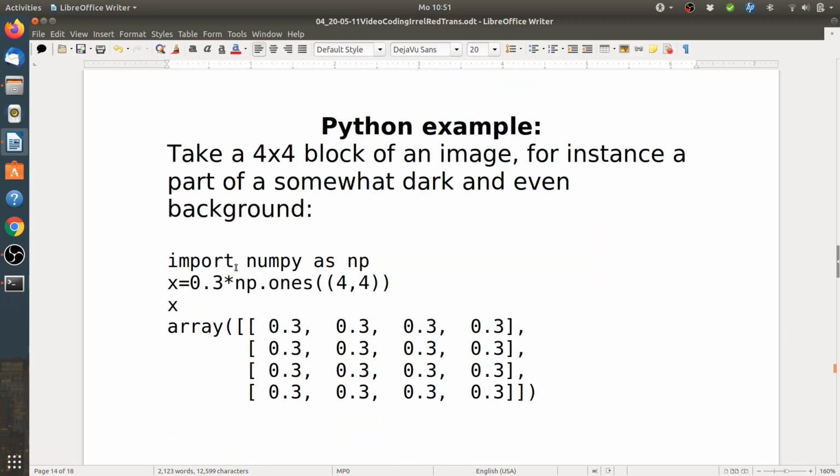This has the advantage that we only have real valued frequency coefficients instead of the complex valued ones of the DFT. And since we have real valued coefficients, that means we only cover one side of our frequency range, say the positive range and not the negative.